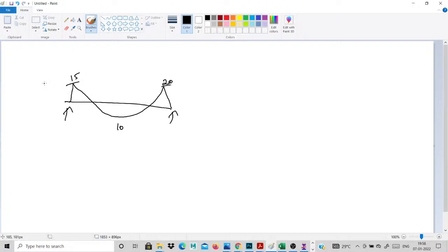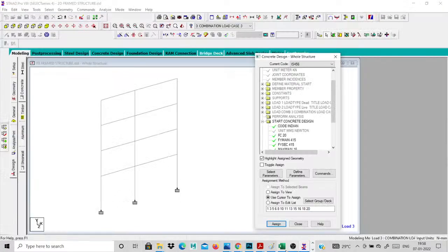So AST, this is the top reinforcement zone and this is the bottom reinforcement. Where the moment is high, the AST will be high, approximately 600 here, approximately 300 there, and approximately 700 for the AST value here. Now it's clear. In the bottom zone, only at this corner the moment is high, so the AST will be high. In the center portion, the moment is lower, so the AST will be lower. Follow the same concept also.